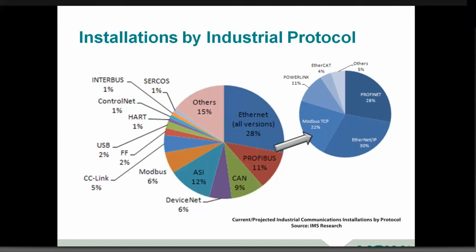I think you've seen some exciting things taking place, and this shows some of what has happened in moving from all of these fragmented field buses. The exciting part is the big push to IP technologies running on some form of Ethernet, whether wired or wireless. The top three are Modbus TCP, Ethernet IP, and Profinet. These do tend to have specific use cases for each of these protocols.